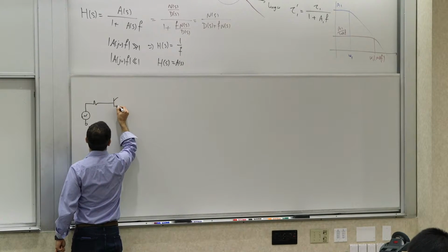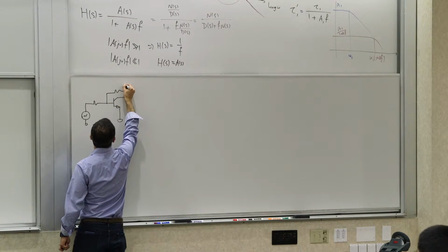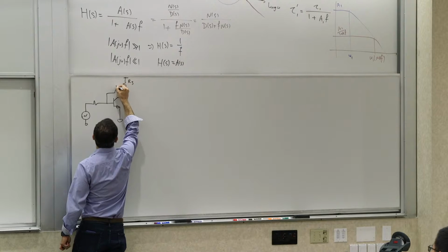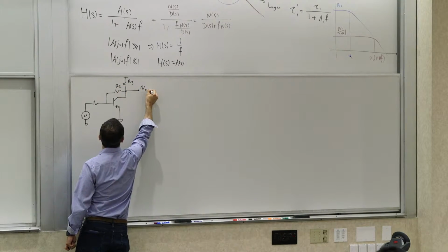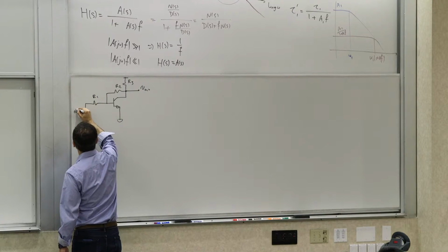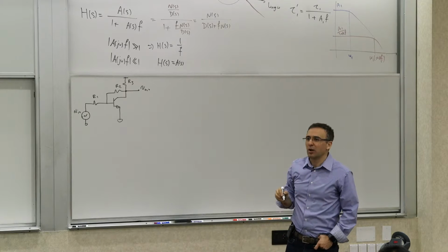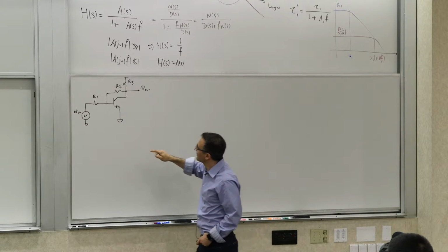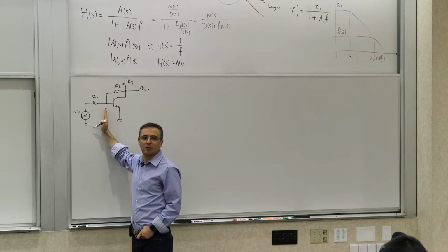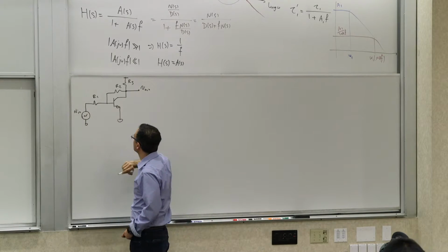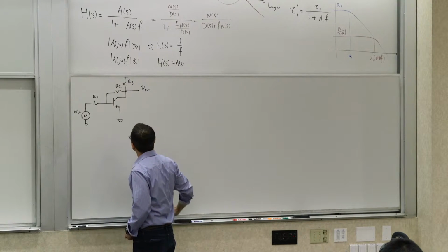It is the transimpedance amplifier stage that we had with R3 and R2, and now you can see why we call them R3 and R2, because I wanted to put the R1 here and apply a voltage source. Remember before, what we had was a current source applied here without this one. Now we are just replacing it with a voltage source in series with a resistor.